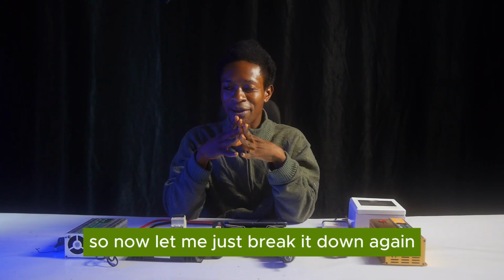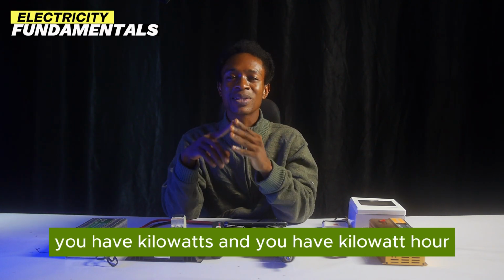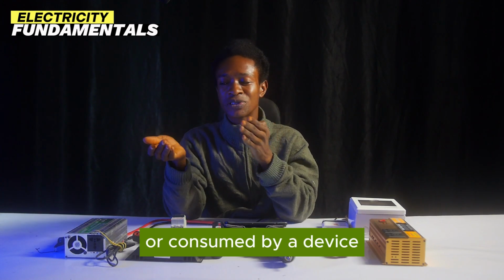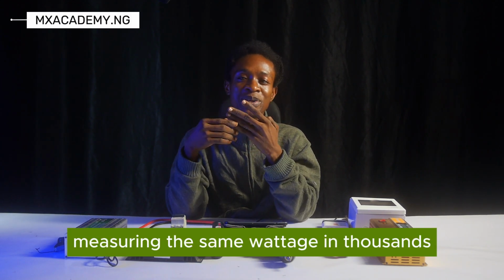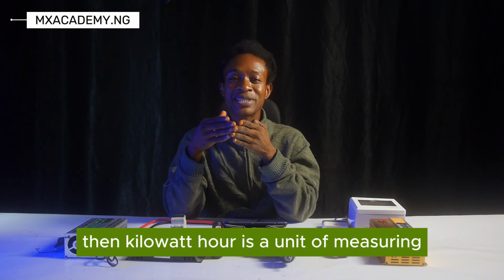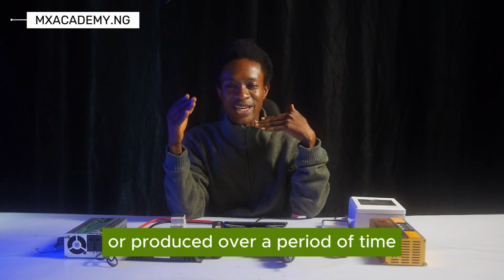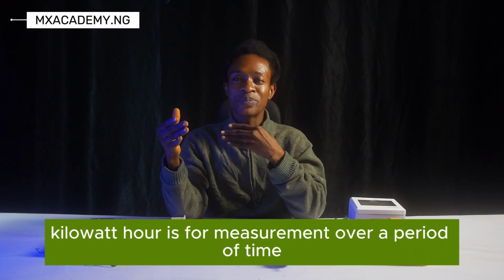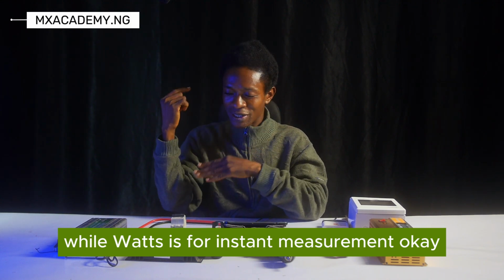Now let me just break it down again. You have watts or wattage, you have kilowatts, and you have kilowatt hour. Watt is an instant measure of the amount of electricity being produced or consumed by a device. Kilowatt is just a unit of measuring the same wattage in thousands. Then kilowatt hour is a unit of measuring the amount of electricity consumed or produced over a period of time. So the difference is that kilowatt hour is for measurement over a period of time, while watt is for instant measurement. I think that's very clear now.